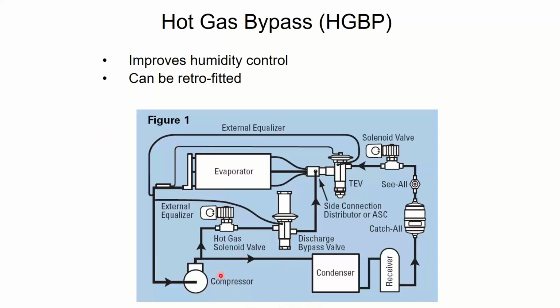What it basically does, without explaining the whole refrigeration cycle, your compressor is supposed to send the hot refrigerant to the condenser outside to throw that heat away, and it does that, but it also takes some of that hot refrigerant and shoves it back into your evaporator coil, which is the indoor side of the system, and it falsely overheats the evaporator coil, which makes the compressor run longer to meet your set point, and hence you get good dehumidification control, but you do it by running your system balls out and overheating things that shouldn't be overheated. It's a Band-Aid. It's not a good idea.